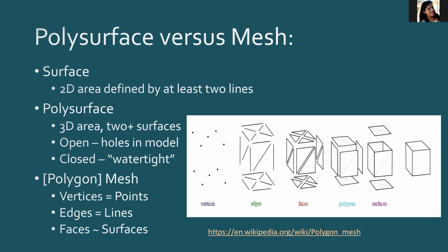So with Rhino, you have a little bit more control over these things, which is good and bad. You can really break things, but I noticed with other programs, they just keep a lot of that behind the scenes. So some of the issues that can occur are faces wind up having their normal pointing in the wrong direction. So just little math things that you have to resolve.